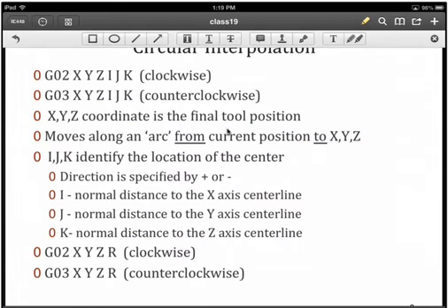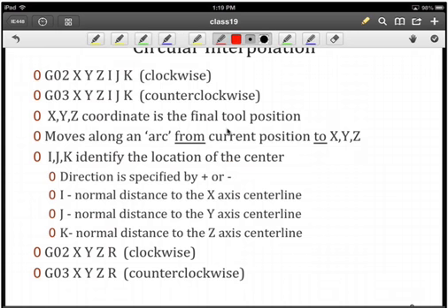Circular interpolation is the same thing. Here, again, we are interpolating along two axes because we are creating a circle in a plane, and we also get this stair-step effect going around the circle, although it's extremely small based upon the precision of the equipment. The two moves that we had discussed earlier were the clockwise move and the counterclockwise move. In that move, of course, we have to specify the endpoint, just like we did for the G01. So that's specified as an XYZ location. So we're going to start at one point on the circle, move to another point on the circle.